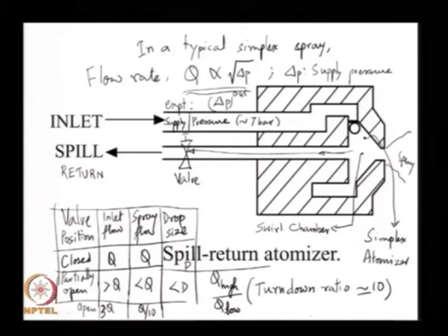So, I am putting in 3 times the flow rate to get a tenth of the flow rate. As opposed to this, if I had a simplex nozzle that was designed to spray Q by 10 with a supply pressure of 7 bar, that would use much lower energy. So, essentially the amount of energy that I am inputting now at this fully open condition is 3Q flow rate at a supply pressure of 7 bar.